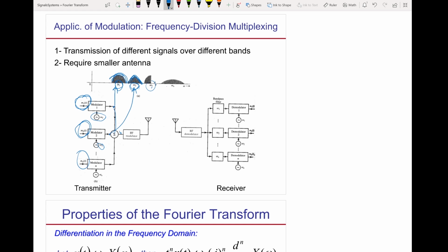Then after you do that, you do another amplitude modulation. So you multiply the whole signal here by a cosine of 1 gigahertz. So you shift the whole spectrum here. Now it's going to be way out here. It could be 1 gigahertz. So what you are getting is this one, and so forth. And then you will have this replica in the negative side. So this is a new carrier, and you transmit.